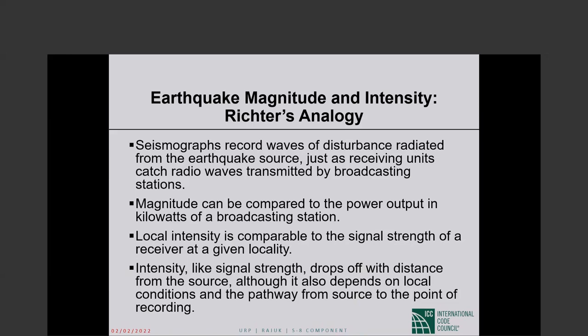Okay? So in the case of an earthquake, magnitude is indicative of the energy released at source. And all magnitude scales are logarithmic scales. So a magnitude 8 earthquake means energy released at source is 10 times that of a magnitude 7 earthquake. But that's what magnitude deals with.